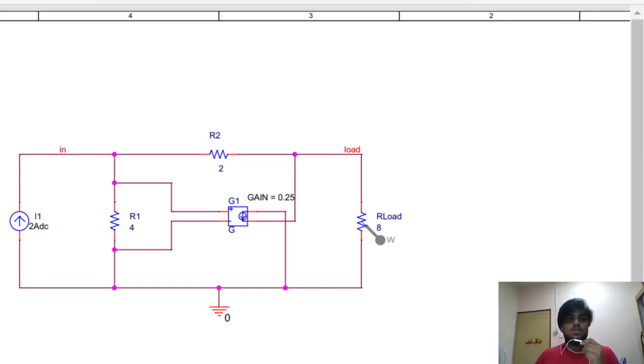Now I'm going to tell you the DC sweep analysis process. First of all, the DC operating point is calculated using a specific start value. The value from the source is incremented, and another DC operating point is calculated. Third, the increment value is added again, and the process continues until the stop value is reached. Then the result will be displayed.